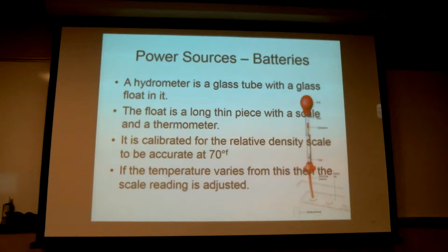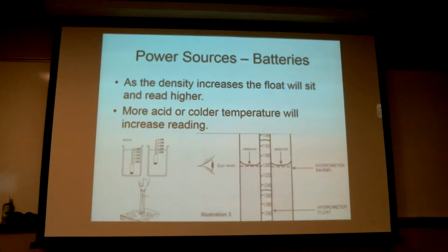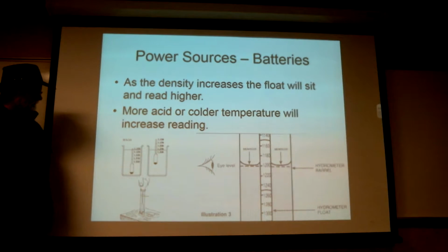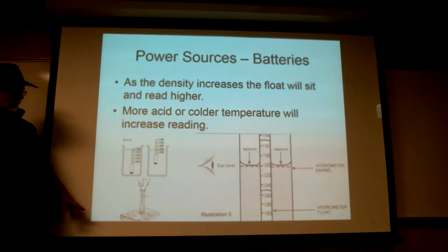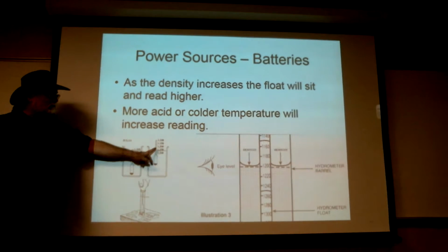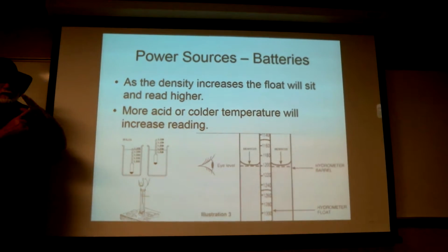You said the FAA answer is 80? I think the FAA test question says you've got something at 40, at 60 degrees. What do you do to calibrate? And I think they're expecting it to be 80. So this just shows the floating. Higher density means the float sits higher, lower means it sits down. All bets are off if the float's sitting on the bottom or it's sticking up so high that it's poked into the cork on top.